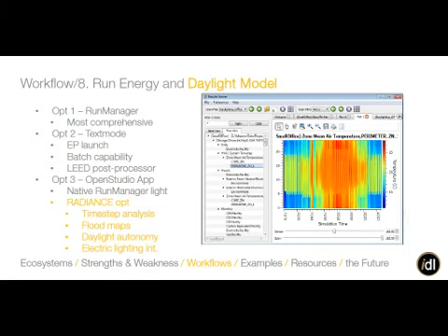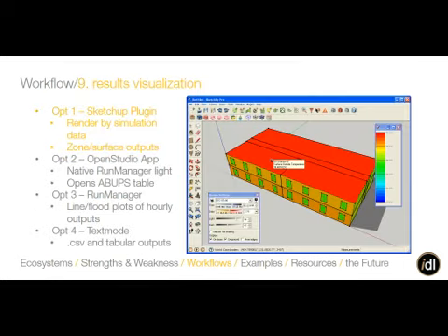Then there's even spatial daylight autonomy, which is a spatial metric, but we won't get into that. But the point is, you can get very detailed analysis within the energy model that can also affect the energy calcs, because EnergyPlus has a native daylight analysis engine, but it's not very good. Generally, one program can't do both, which is why it has to link to Radiance. In this case, you get the best of both worlds.